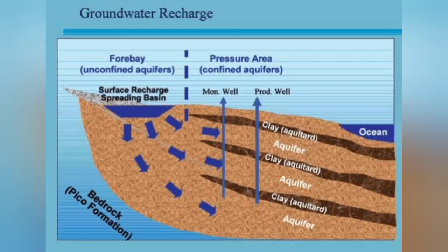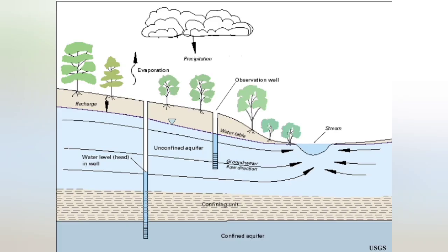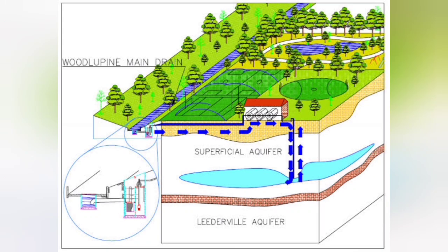Assessment of subsurface potential for groundwater recharge. So, based on the hydrological and geophysical surveys, the thickness of the potential unsaturated zone for recharge should be worked out to assess the potential for artificial recharge in terms of volume of water which can be accommodated in the zone. Like source water availability, the studies should bring out the potential of the unsaturated zone in terms of total volume which can be recharged.